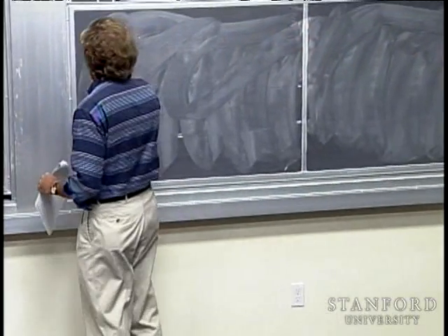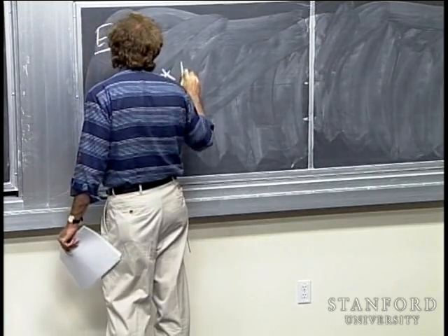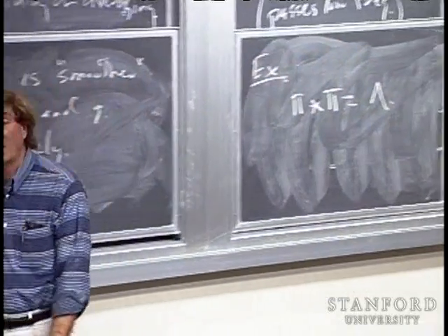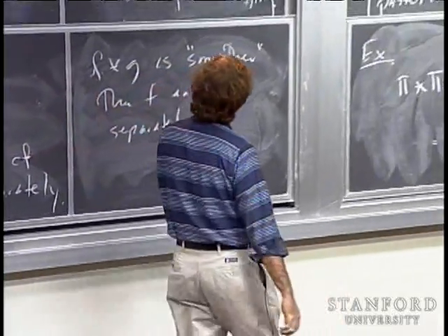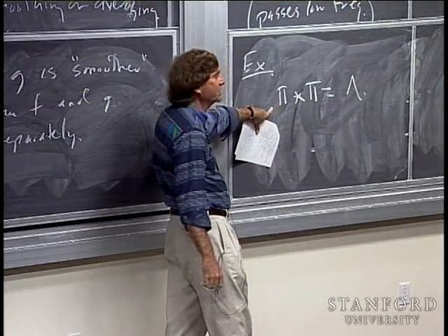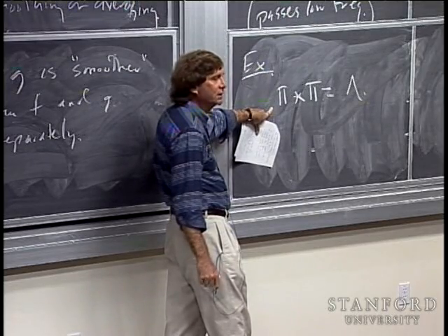One example is if I take the rectangle function and I convolve it with itself, I get the triangle function. Now, you have to work on this with a scaled rectangle function, where you actually have to compute this by evaluating the integral. We actually have to do that once in your life, and probably only once. You should compute a couple of convolution integrals and see how it works out.